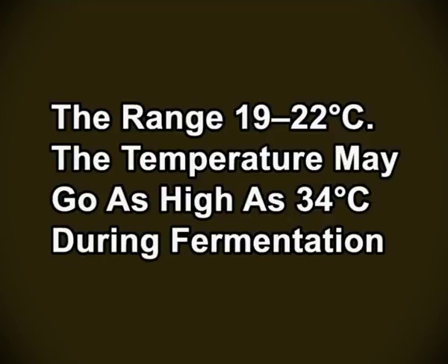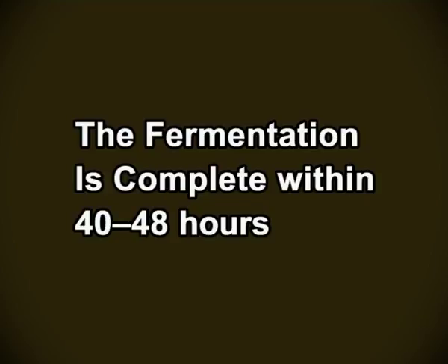The temperature may go as high as 34 degrees Celsius during fermentation. Hence, the need for ale based strains rather than lager based ones. Typically, the fermentation is complete within 40 to 48 hours. Some advocate holding a few hours prior to distillation in order to ensure that the endogenous lactic acid bacteria have an opportunity to enhance flavor.